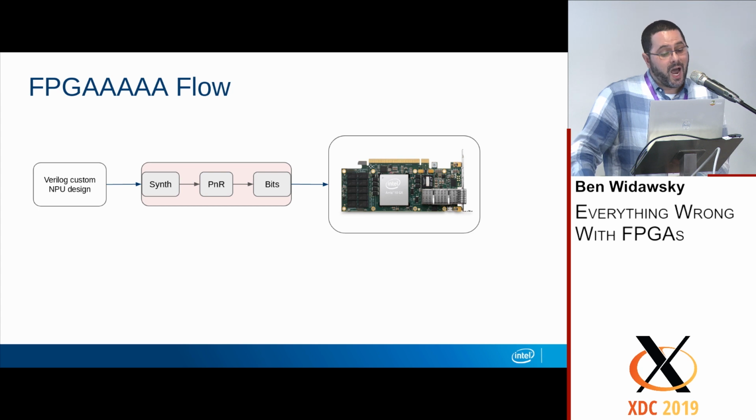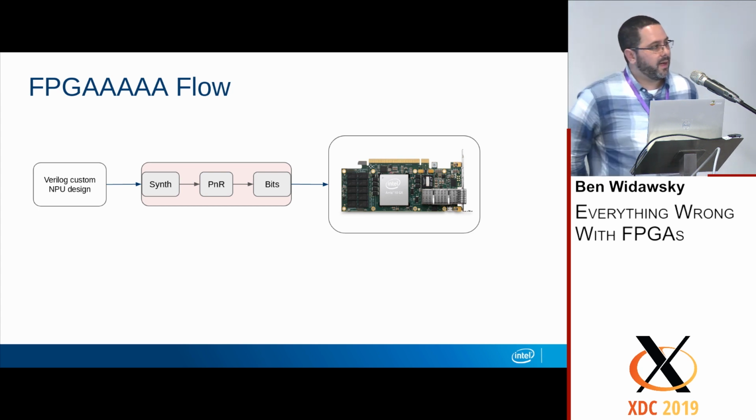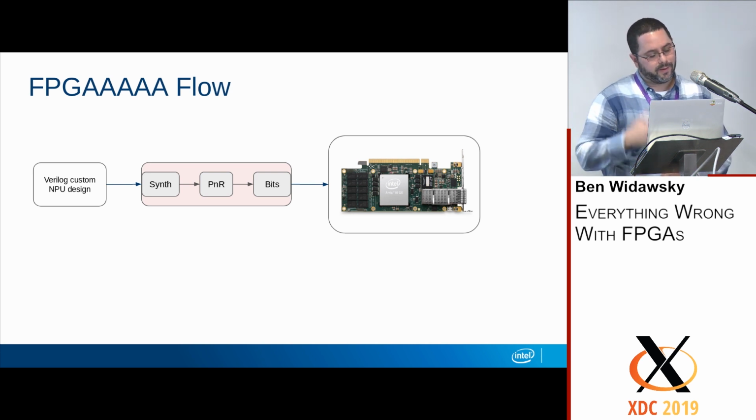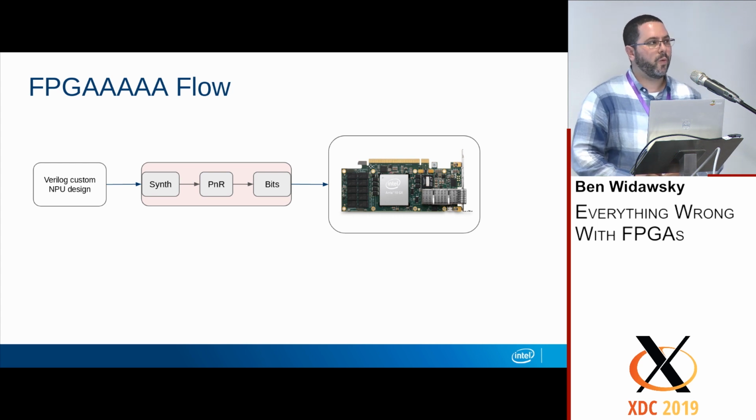The second FPGA flow is an interesting one. So you make your custom design in Verilog, or whatever language, and you synthesize that, and it's running on your FPGA. And one of the issues with that today is that, at least according to some of the information I have, doing the synthesis for an FPGA for these custom NPUs can take on the order of a week.